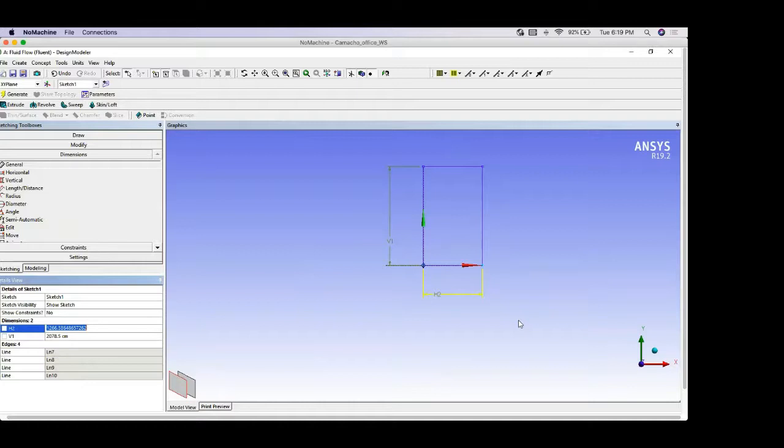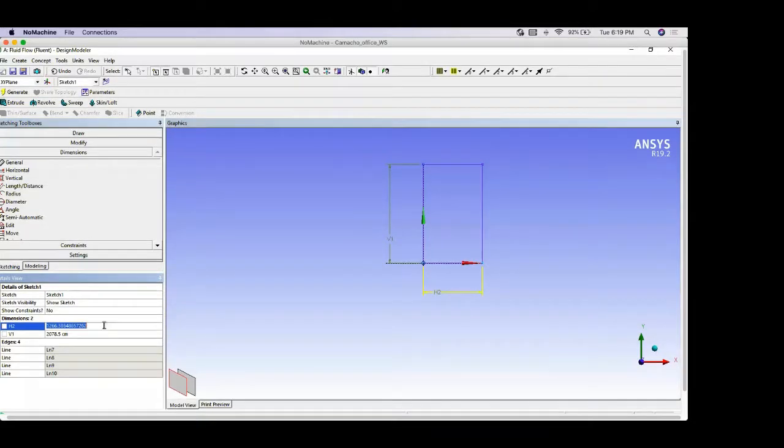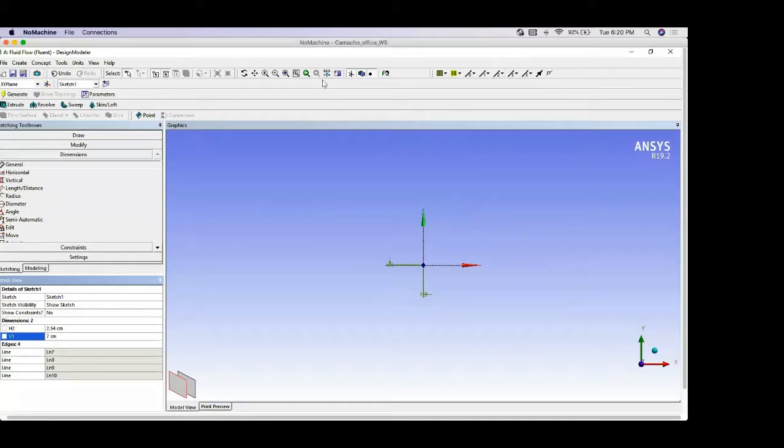So just asking. So we usually work with a separation distance of about 1 inch between the nozzle and the stagnation plate. So our horizontal distance here would be 2.54 centimeters. And vertical, usually I use a 7 centimeter domain, 7 by 2.54 centimeter domain, just because I'm kind of giving it room for the flame to look prettier.